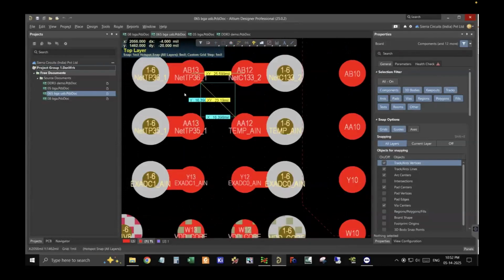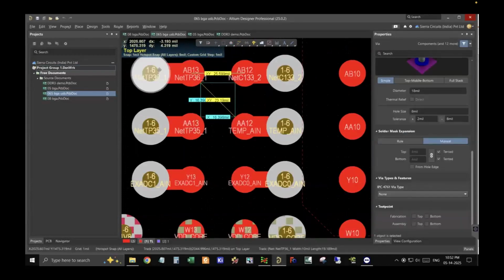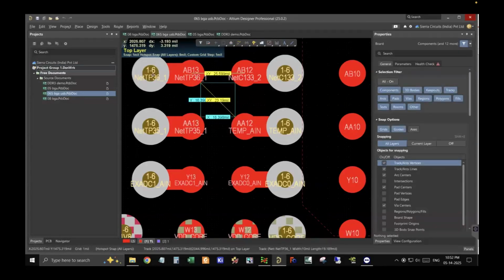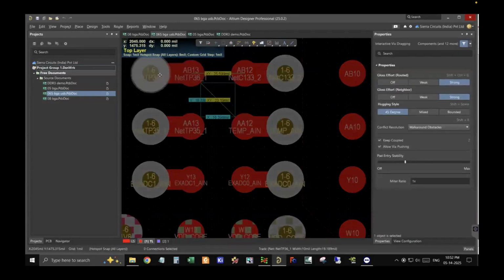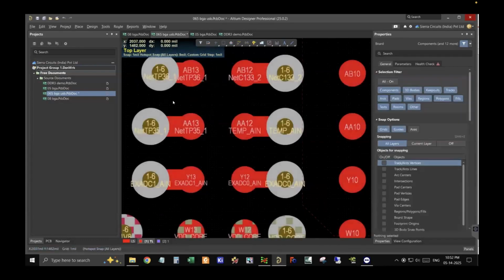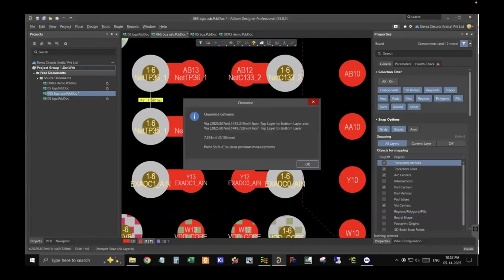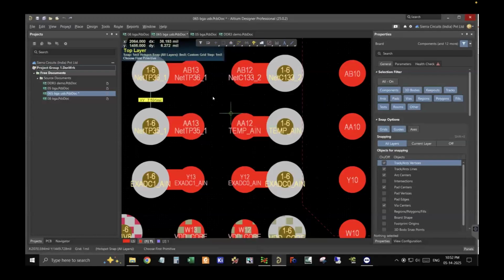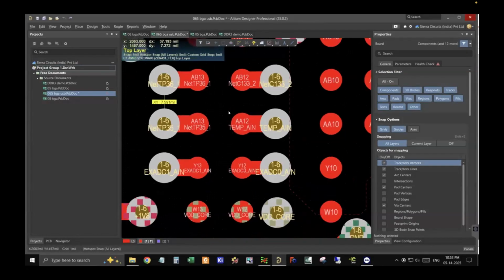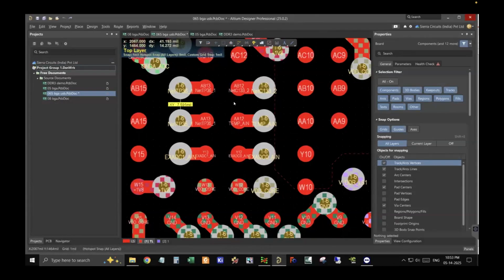Otherwise, as I said, you can also place these wires on the pad directly if the space is not enough. As you can see, suppose I move this over here. Suppose now this was placed on these two pads, then you will be left with a spacing of 7.5 mil. That should be perfectly fine. So wire on pad is another solution. And if everything doesn't work, then you have to go with blind and buried wires.